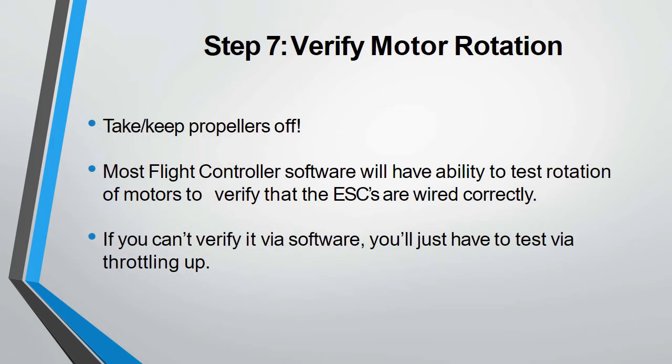Next step, verify motor rotation. Keep propellers off. Most flight controller software will have the ability to test rotation of motors to verify that the ESCs are wired correctly. And then if you can't verify it via software, you will just have to test via throttling up.